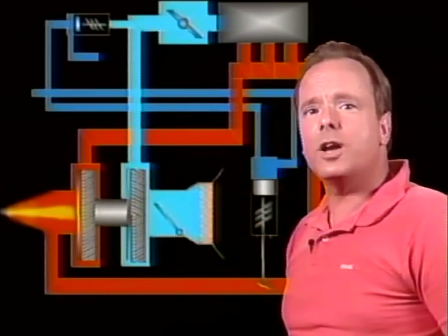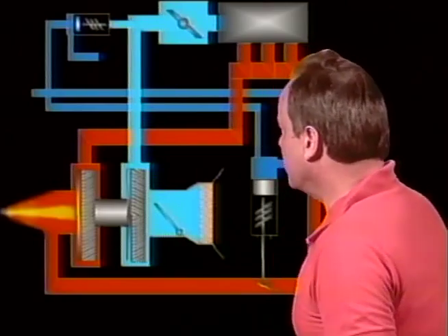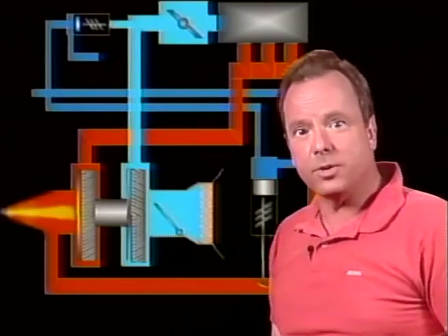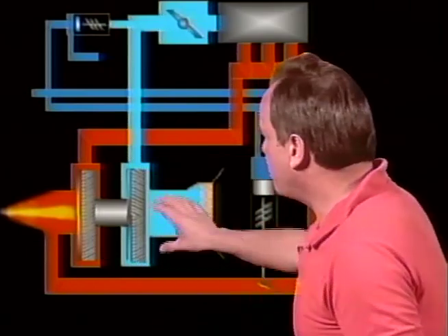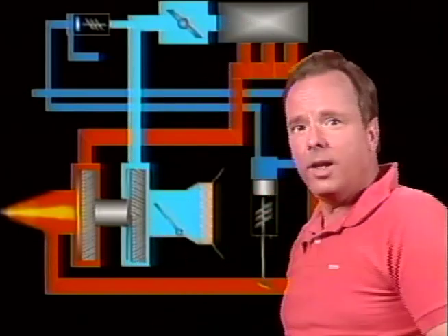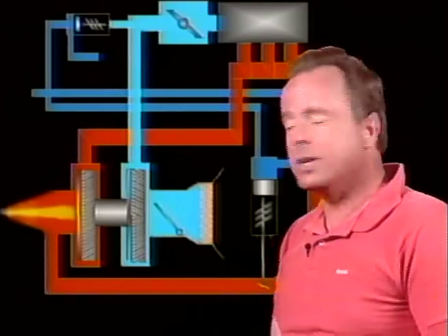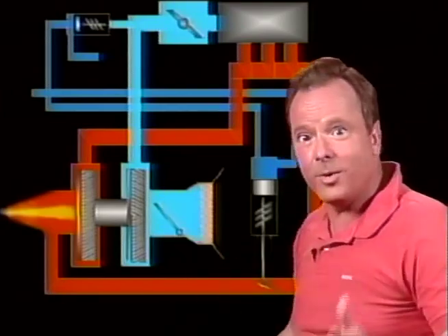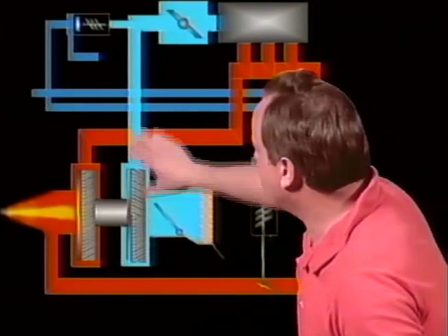Now they ask you just one or two maybe questions about superchargers on the FAA written exam, so you need to know what a supercharger is. Well, a supercharger does exactly the same thing. It compresses the air going into the engine, and actually it compresses the air after it's mixed with fuel, but that really doesn't matter. It's not a question they ask you, but it compresses the fuel-air mixture going into the